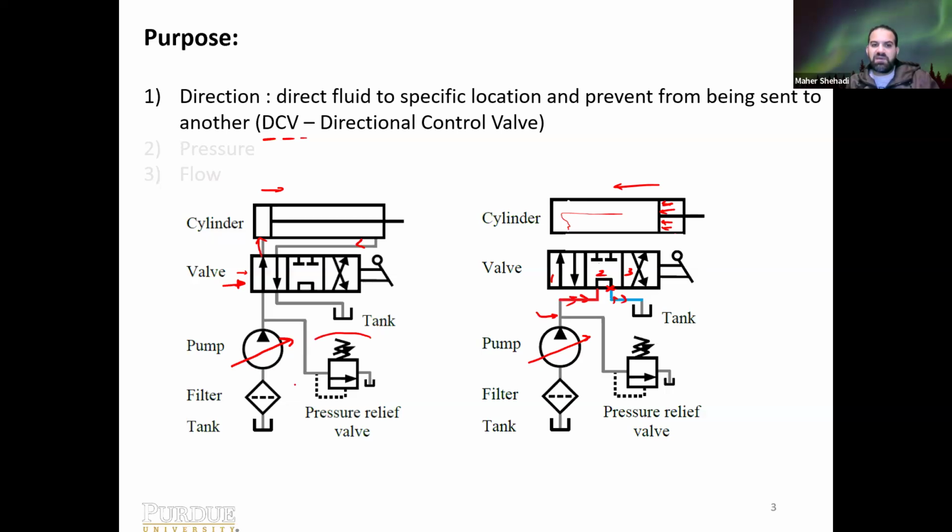That's why we need some kind of protection, and that's the second type, when we will be talking about pressure relief valve and pressure reducing valve. So usually in systems, we do need to have a pressure relief valve, and it should protect the system. We put the pressure relief valve next to the highest pressure point inside the system, which is the pump. That's where the highest pressure is. After that, you have pressure drop across the lines, across the valves, the DCV for example, elbows, and so on. So pressure starts dropping as we move on.